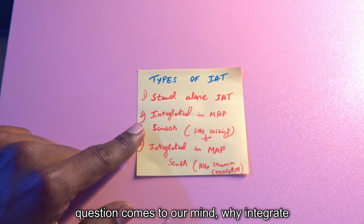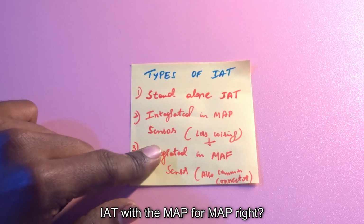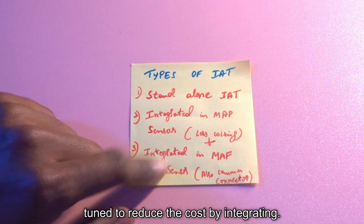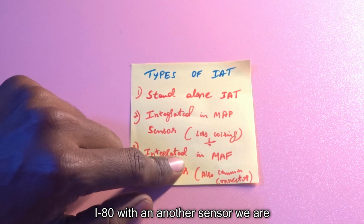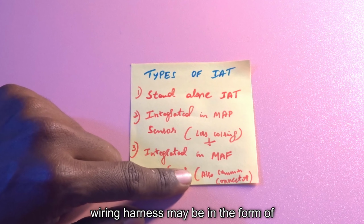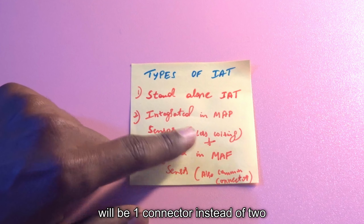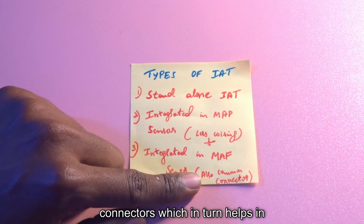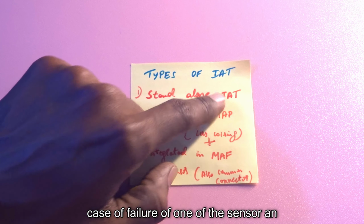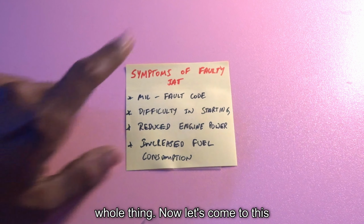Now a question comes to our mind: why integrate IAT with the MAP or MAF, right? This integration of the sensor is mainly done to reduce the cost. By integrating IAT with another sensor, we are reducing the number of wires in a wiring harness, maybe in the form of common ground or common power. Also, there will be one connector instead of two connectors, which in turn helps in reducing the cost. But the drawback is, in case of failure of one of the sensors in the integrated type, we have to replace the whole thing.